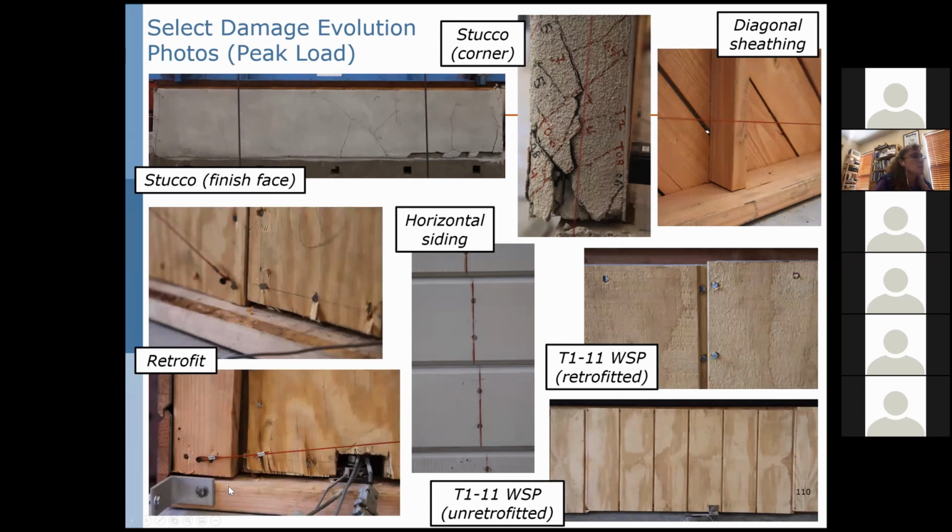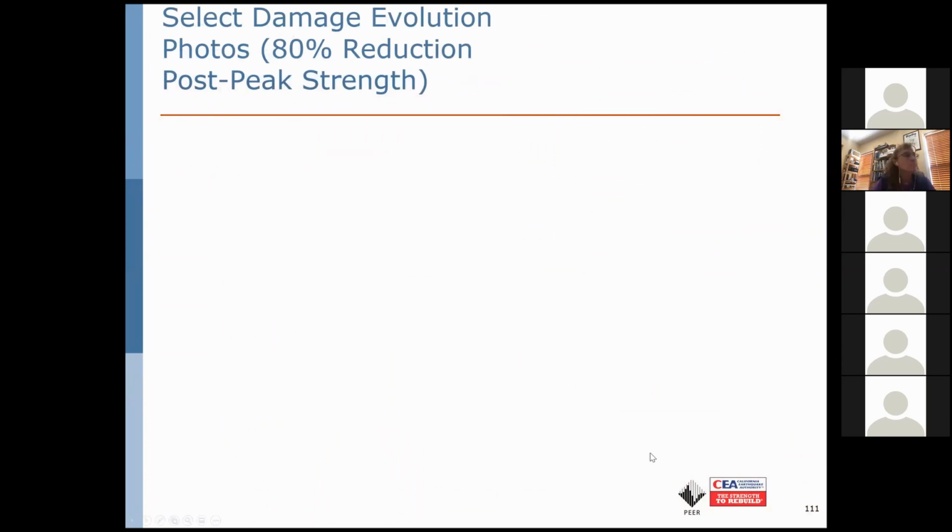And appreciable damage in the case of retrofit, as one would expect, to the fasteners, incipient pull out, and in some cases pull through, and crushing at the end of the plywood as it bears to the flat 2x at the end of the specimen and at the sill plate location. You can see the skirt style crushing occurring here.